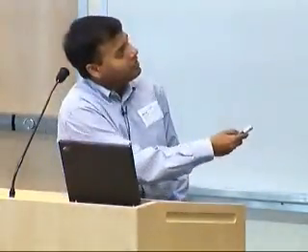So going back to my previous point of who cares about soft errors, as we said over here, if you had a 20,000 processor server farm, you could have roughly one major flip-flop error every 20 days. And this measure has a meaning. People have done studies showing that most soft errors do not matter at a system level. It's only roughly around 5% of the soft errors that really matter at the system level.